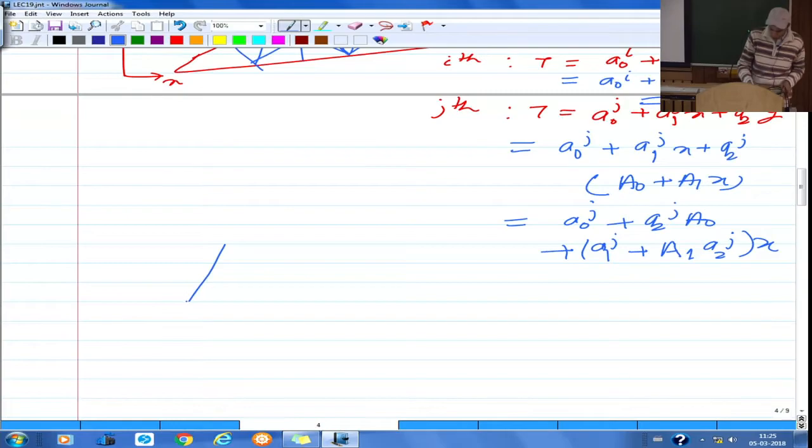So I will have one element going like this and another element sharing the common boundary going like this. Here I will have 6 nodes like this, and here also I will have 6 nodes like this. These 3 nodes are common to both these elements, and the temperature variation within each is assumed to be quadratic.